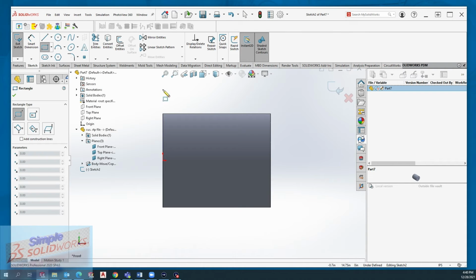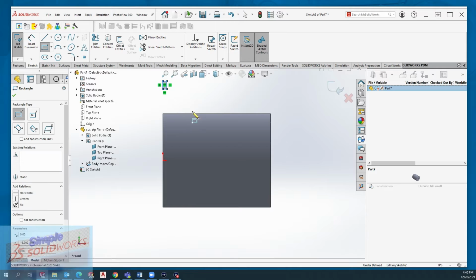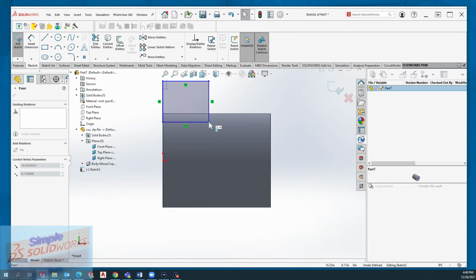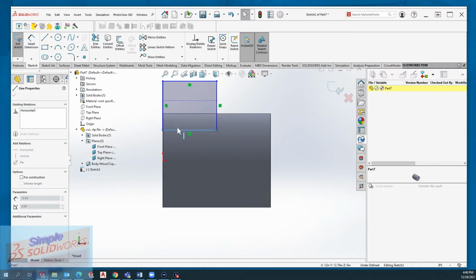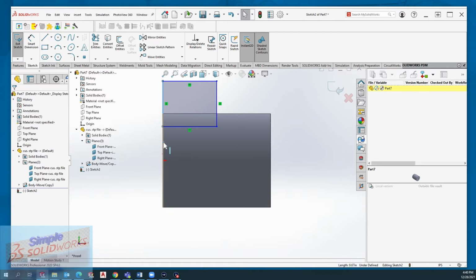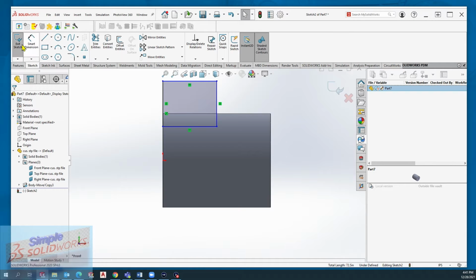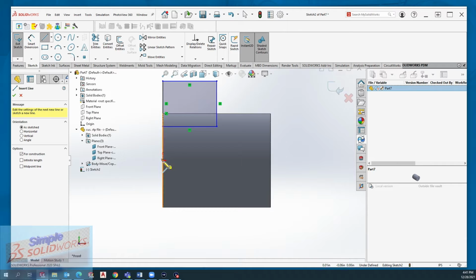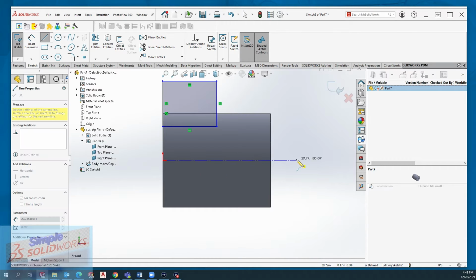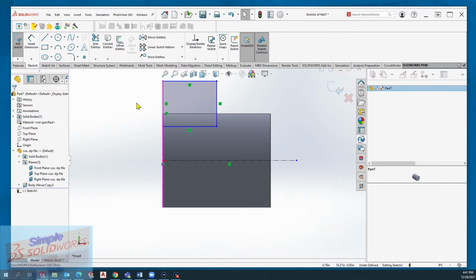So you start your process here. And you can physically move it like this. I like to make sure that this and this are collinear, this line and that are collinear, so that it matches, is on that face. It's constrained. I also like to make a center line to the center of the circle or to the UCS, right? And then I like to start my dimensioning.